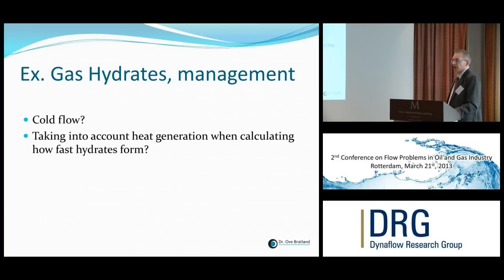We have also seen other exciting developments. For instance, cold flow for hydrates. There's been a lot of research work on that. Can we transport hydrates in the flow line? Instead of stopping it from forming, we allow it to form, and then we transport the whole thing. It has been difficult to do so. Quite a lot of money has been spent on finding ways to do it.